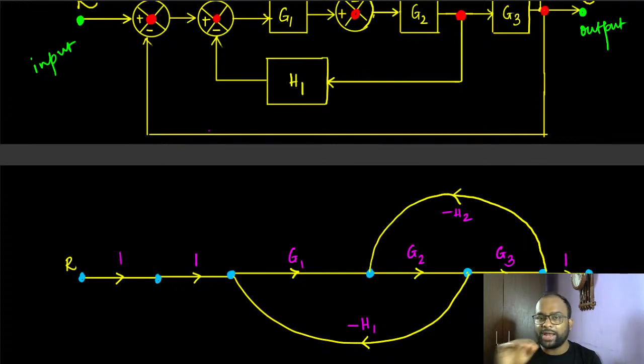If you are trying to send a signal to a device through that pin, and the device is drawing more than 40 milliampere, what is going to happen? The microcontroller won't be able to deliver the current. The internal resistance will resist that. It won't be able to deliver more than 40 milliampere of current.